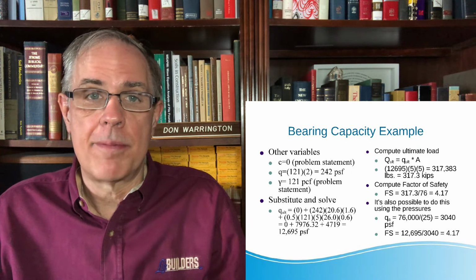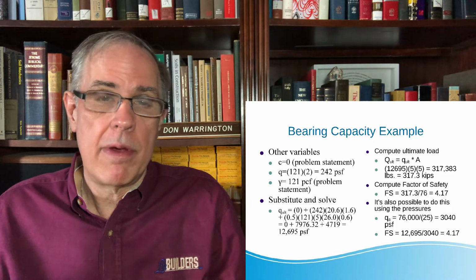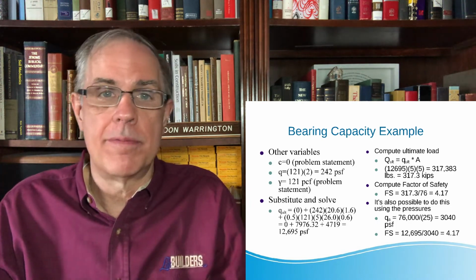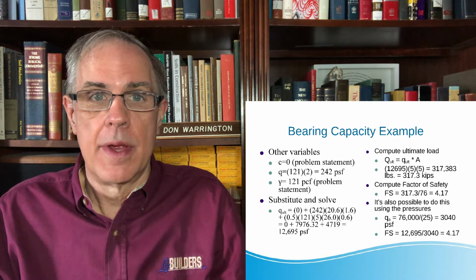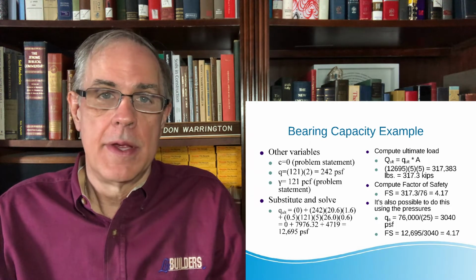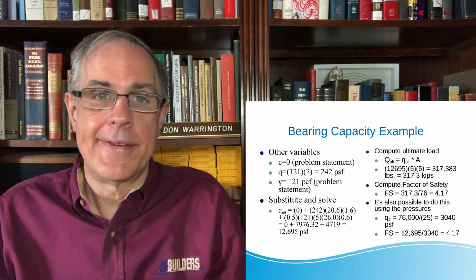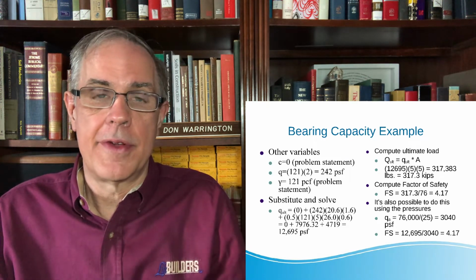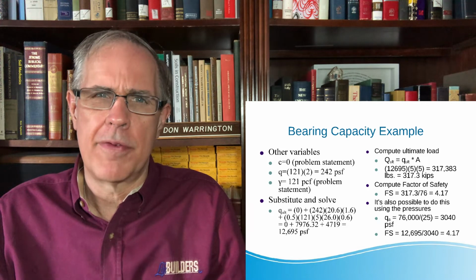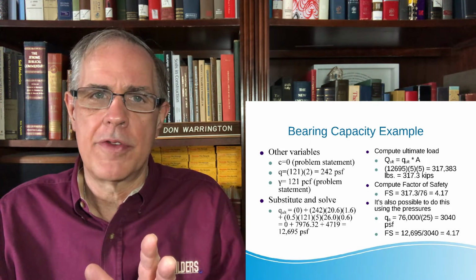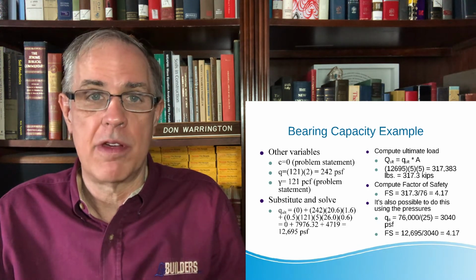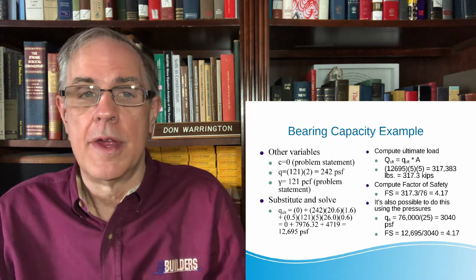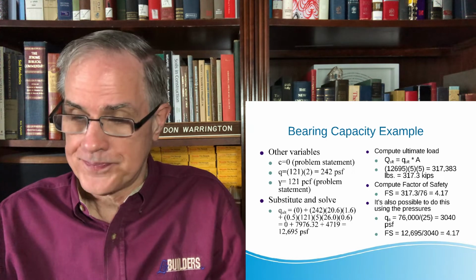Because, for example, you excavate down to the depth, and then you pour the foundation, and then they throw the soil on top of it, and they may not be as careful. So the soil on top of it, for example, could be 115 or 110 PCF, in which case your overburden is less. So you have to take that into consideration.